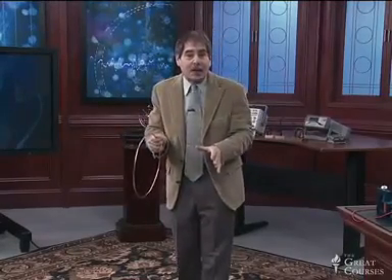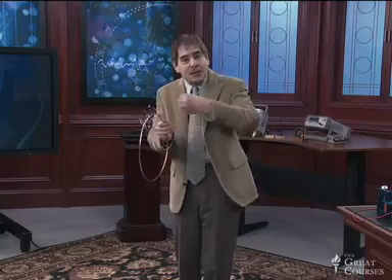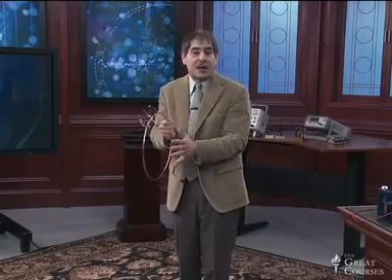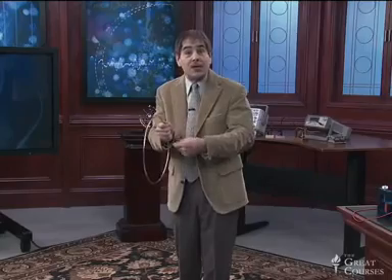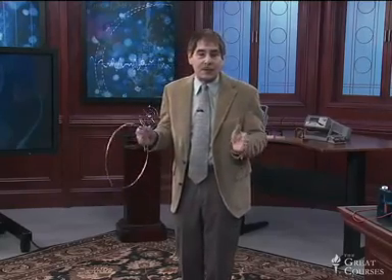So there's a magnetic flux through this circuit caused by the circuit's own magnetic field, caused by the current that's flowing in that circuit. But we know that changing magnetic flux creates electric fields, and those electric fields oppose the change that's giving rise to them. So if I'm trying to build up the current in this loop, starting at zero, as soon as I try to change the current, I create a changing magnetic flux in this circuit itself. And that changing flux is going to oppose the change that gave rise to it, namely the buildup of current. And the net result is it becomes difficult to build up currents in circuits.